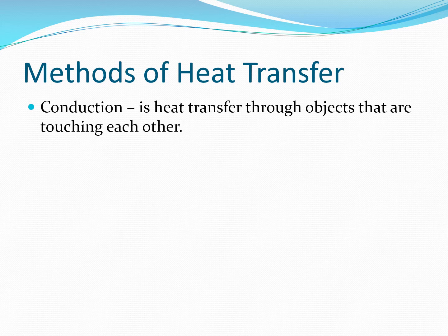These are all things that we are used to, but we just don't think about all that often. Conduction is heat transfer through objects that are touching each other. If I were to apply this into automotive, we think about the items that are in an engine, and since they're touching each other, heat is transferred from one part to another because they're touching each other. So an exhaust manifold is going to be hot because it is bolted to a cylinder head, and the cylinder head is right above the heat expansion when the air and fuel is exploded. So that is done through conduction. They're touching each other.